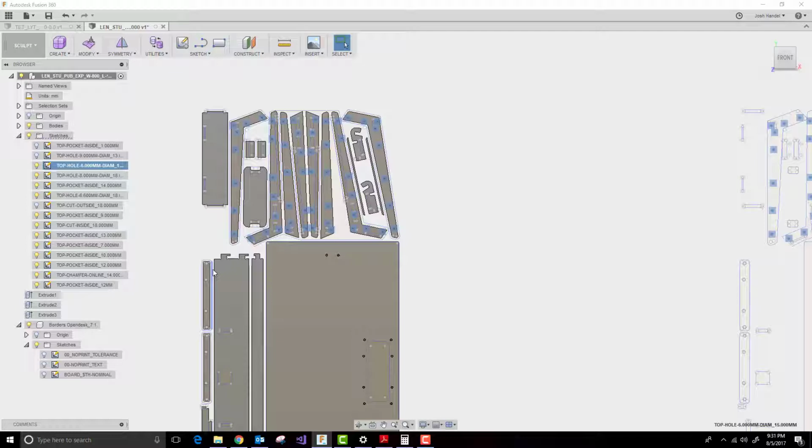This is 15mm long. 30mm long is what they want because they usually cut 15mm deep. But you can find that. That's easy material to find, and you can just use your 1/4" bit. So you don't have to worry about, oh my gosh, 6mm and have to go get a new end mill. Just use your 1/4" end mills. You'll be fine. All of the dog boning and everything is designed to fit a minimum of a 1/4" end mill.